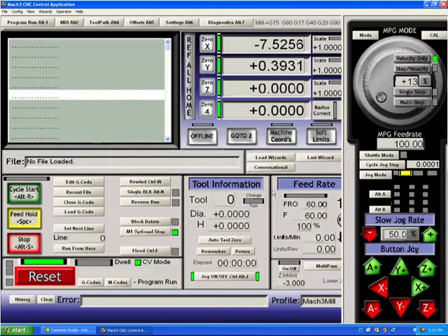And what that does is give you two speeds of jog. Just hitting the arrow keys on your keyboard, you can see I've got a speed of approximately 10 millimeters per second being fed. If I press the Shift key at the same time, I now go to fast jog, and I have 20, which is twice the slow jog. In other words, slow jog is 50% of the maximum rate, and you get the maximum rate by pressing Shift. Notice when I press the Shift key that the fast jog indicator lights up. Otherwise, you're on normal speed.